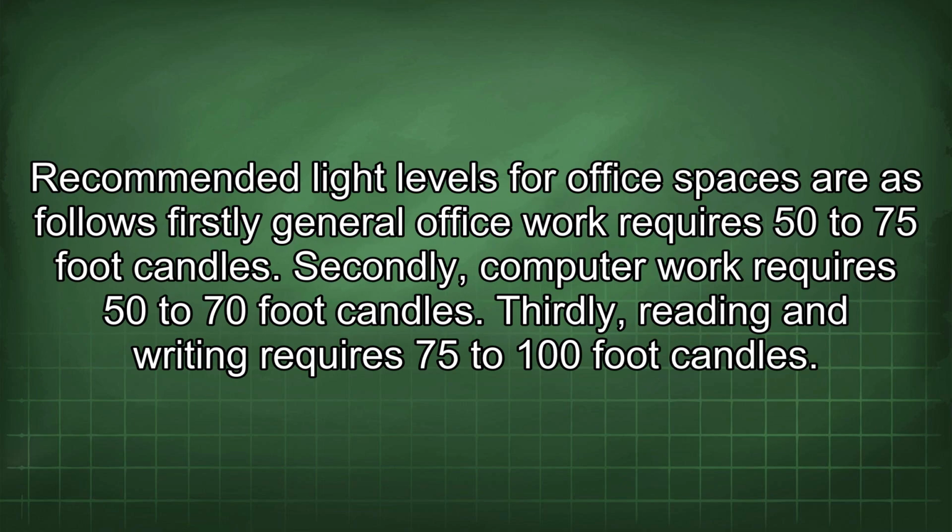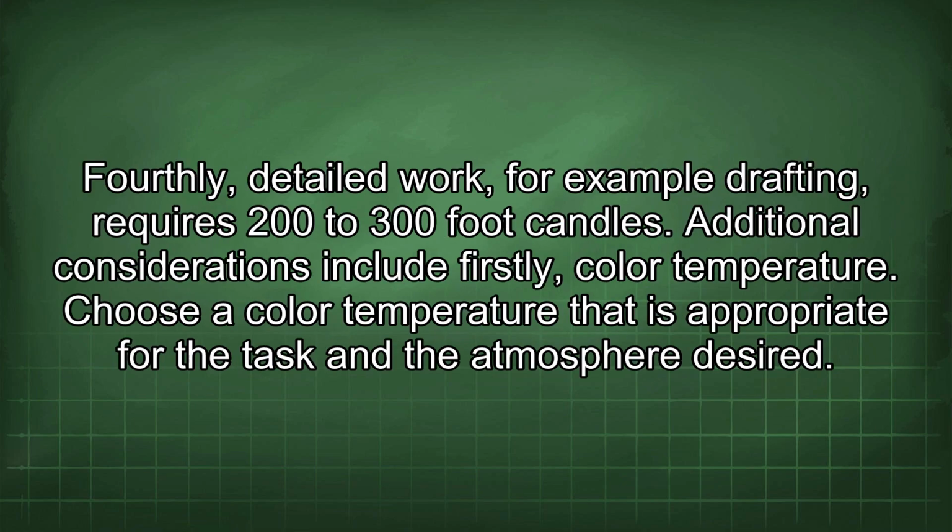Recommended light levels for office spaces are as follows. Firstly, general office work requires 50 to 75 foot candles. Secondly, computer work requires 50 to 70 foot candles. Thirdly, reading and writing requires 75 to 100 foot candles. Fourthly, detailed work, for example drafting, requires 200 to 300 foot candles.